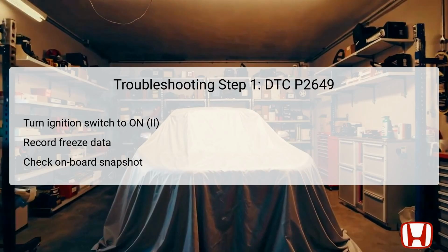Next, it's imperative to record all freeze data and any onboard snapshots. This data can provide crucial insights into what the vehicle's systems were experiencing at the moment the DTC was triggered. By reviewing this information, technicians can pinpoint when the issue began and correlate it with any observed symptoms. Finally, familiarizing oneself with general troubleshooting information specific to the Honda Civic can streamline subsequent diagnostic steps.